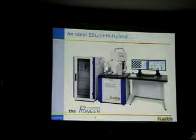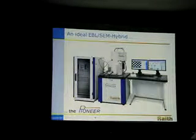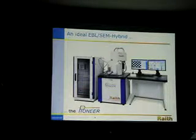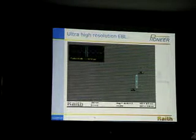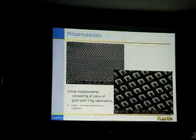It's also the perfect EBL-SEM hybrid. Remember, you can take an SEM and convert it into a lithography system. Well, here we have what we call the perfect EBL-SEM hybrid. So it's capable of very high resolution lithography. These are 20 nanometer lines. And remember, these can be stitched together over large areas. So very high density lithography using field emission electron source technology.